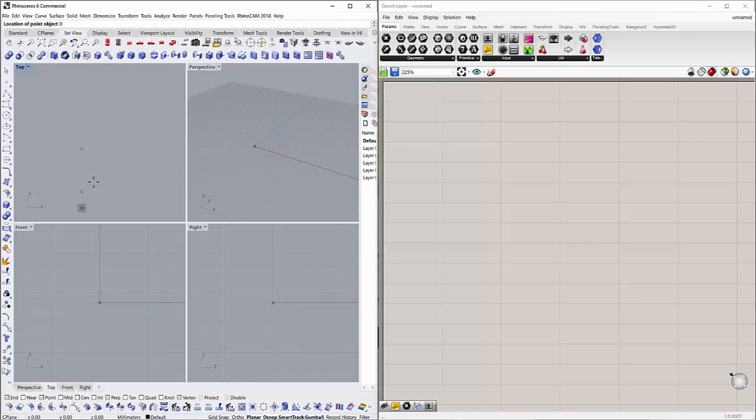So I will enter 0, 3600, 0. As you can see, I created a set of 4 points. This is for one single mullion. So I'll select all of them, copy it, paste it here again, and then move it from this base point to here 1780 mm far.